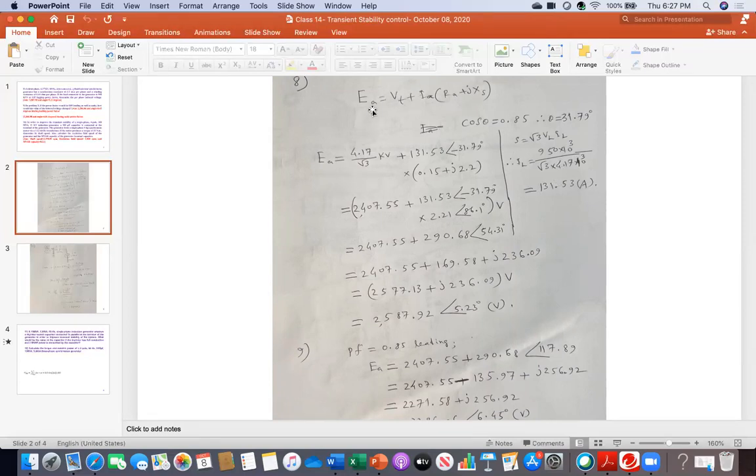No. So you see, when I am writing this equation, that is the per phase equation. So that's why here you are dividing. But in this equation, when calculating I_L, that is S equals root 3 V_L I_L, that is the three phase apparent power. And of course, those are the line quantities. Always for every problem, S equals root 3 V_L I_L uses line quantities.